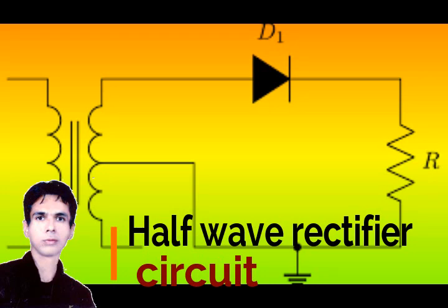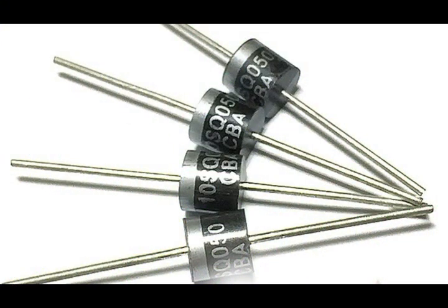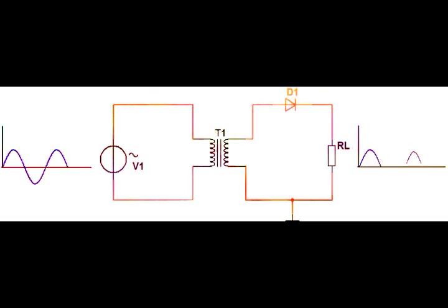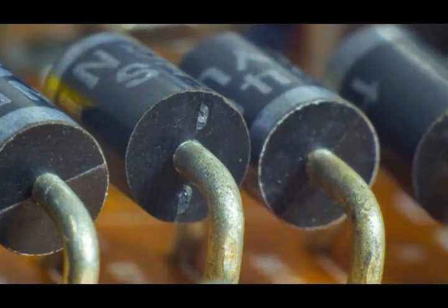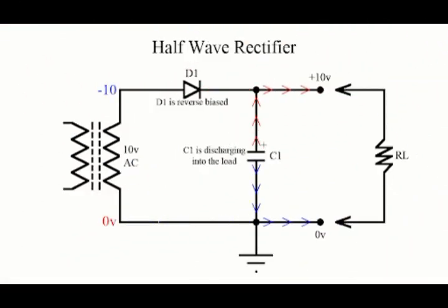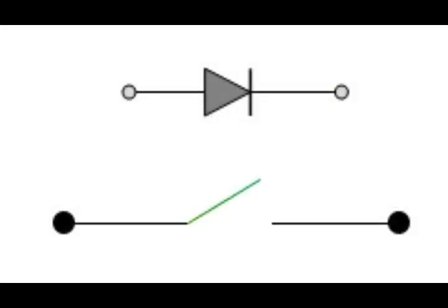Half-wave rectifier circuit. All single-phase rectifiers use semiconductor components. Single-phase uncontrolled half-wave rectifiers are the simplest and perhaps the most widely used rectifier circuits for low power levels because they are not affected by the connected load impedance. In uncontrolled rectifier circuits, semiconductor diodes are the main components and are arranged to form a half-wave or full-wave circuit. The advantage of using diodes as a rectifier component is that, depending on the design, they are unidirectional components and have a unidirectional PN junction.